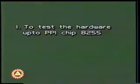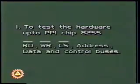If there are any malfunctions, we analyze signals, read bar, write bar, chip select, address, data and control buses and rectify the faults. In the second step, we integrate and test the analog to digital converter ADC 0801 with the transducer.